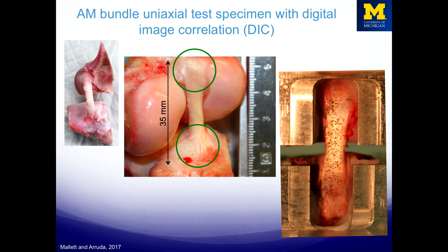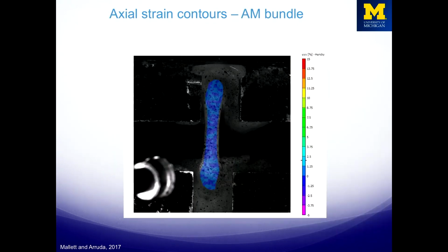So from that, you're measuring strain directly on the tissue surface, okay? So we did this experiment, and I'll show you. Once you post-process and you have the displacement fields and then the strain fields, you can convert them into color-coded strain contours, okay? So as I pull on this, we'll see the colors change as the strain increases.